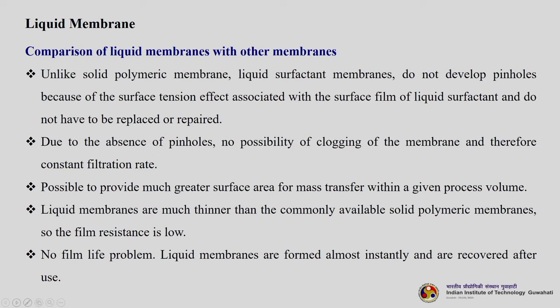It is possible to provide much greater surface area for mass transfer within a given process volume. Liquid membranes are much thinner than the commonly available solid polymeric membranes. So, the film resistance is low. This is also another advantage, and there is no fouling-like problem. Liquid membranes are formed almost instantly and they are recovered after use.